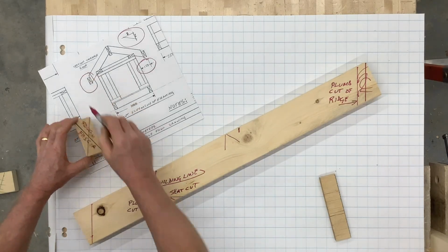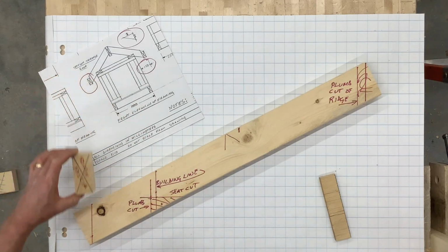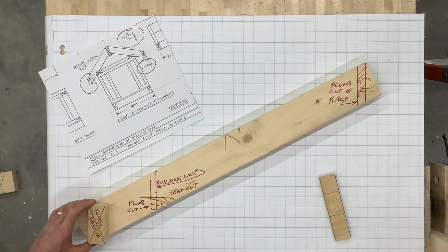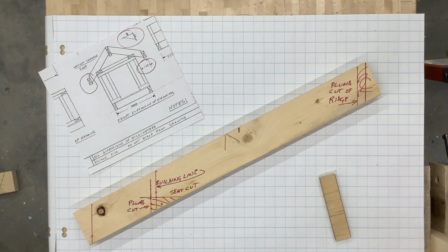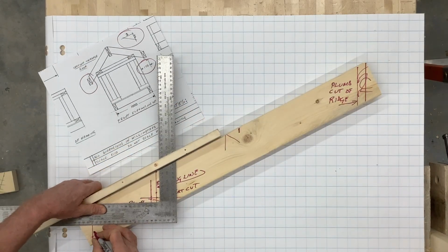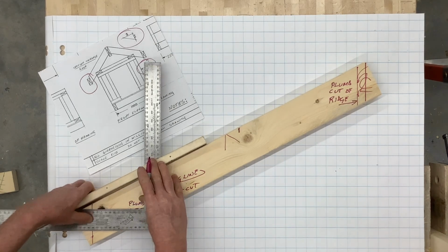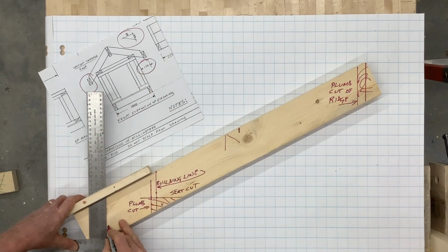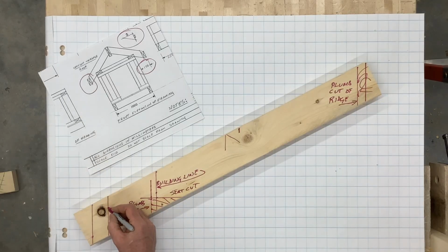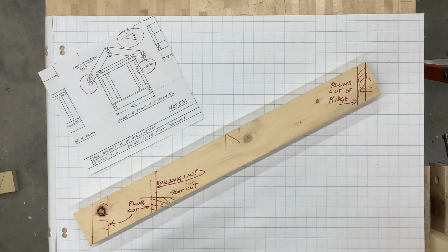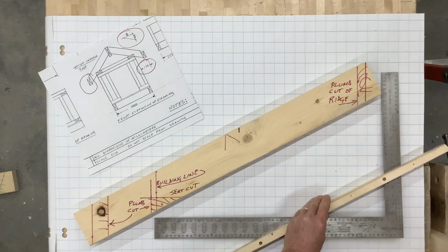Finally, we'll do the adjustment for the rough fascia. For this rafter, we need to deduct the 38 millimeter thickness of the rough fascia from the 150 millimeter projection of the rafter tail. With the framing square, measure back 38 millimeters along the horizontal and make a tick mark. Remember, never measure these adjustments along the slope of the rafter. Always measure perpendicular to your plumb lines. Strike a plumb line through your tick mark and you have the plumb cut line of your rafter tail. There's your layout, all done.